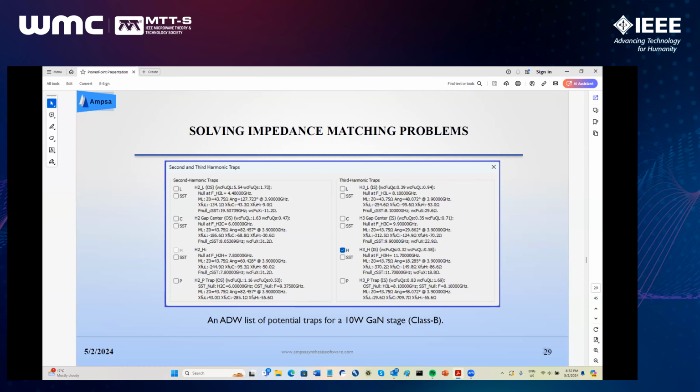Here we have reactance values. The fundamental reactance is sort of in the order of 30 ohms. So this thing will at the highest frequency give me an extra 53 ohms loading, 99 ohms, 250 ohms. So basically it will load me fairly significantly. 30 ohms is not far away from 50 ohms, so the loading is not insignificant at the fundamentals. This one which I selected, the loading is 80 ohms. That's fairly much bigger than 30 ohms. 140 ohms and 370 ohms.